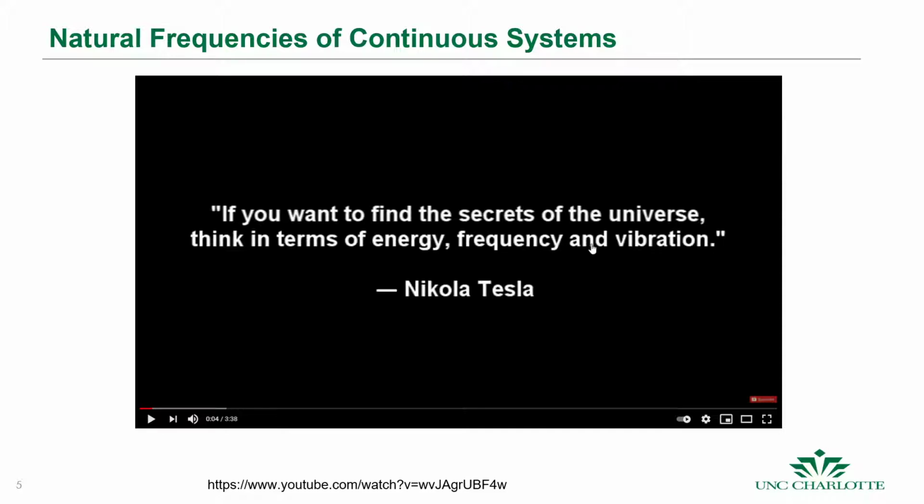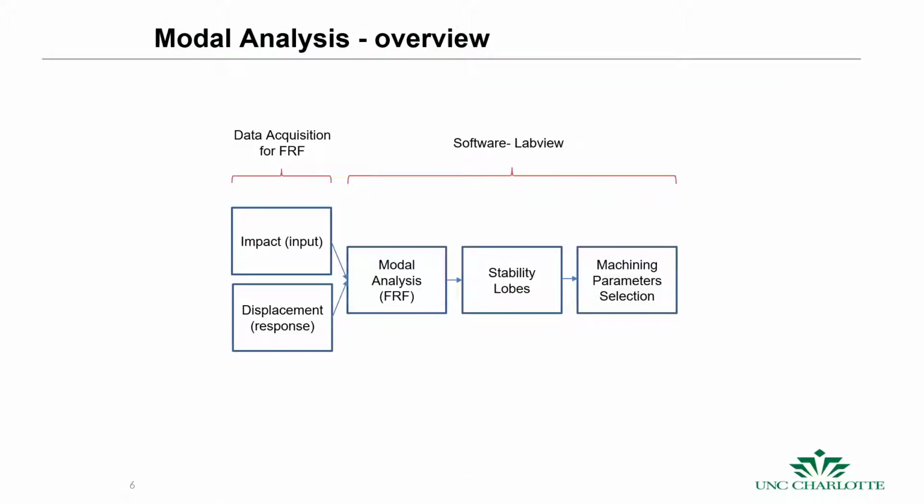So for our purposes, we don't necessarily have to consider all of these things initially, but if we have a machine that will be subject to vibration loading, then it would be important to do the structural analysis and look at the various mode shapes and the excitation mode shapes, because it can have a very important role in fatigue, particularly failure.